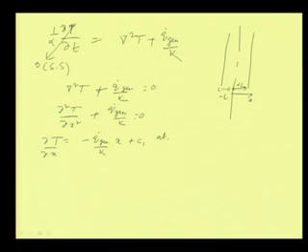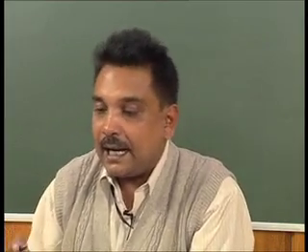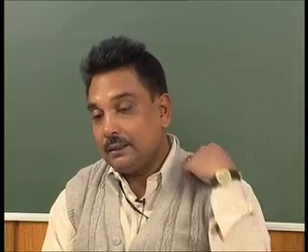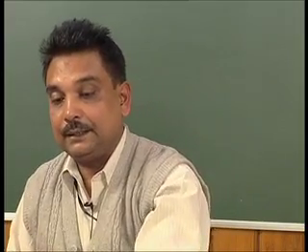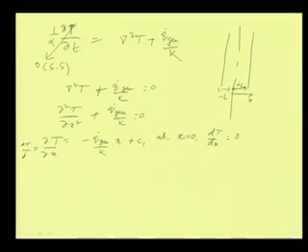Understanding the homogeneity, that it is uniformly heated, and the symmetric nature, because it is the center line, at x equal to 0, dT by dx will be equal to 0, because of the symmetry of the system.